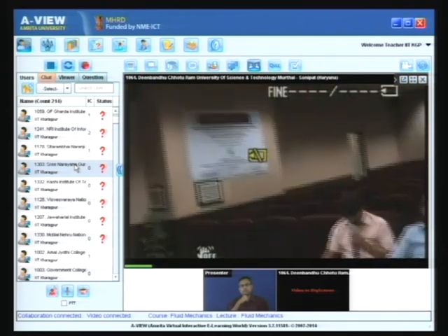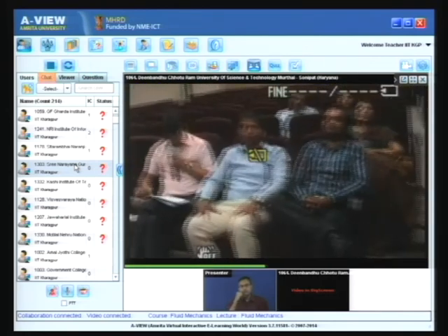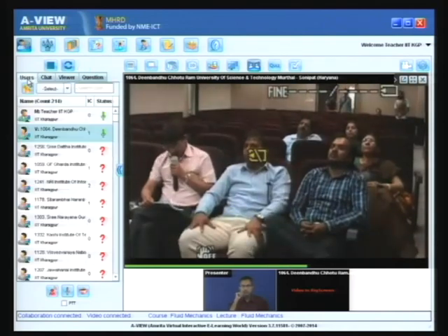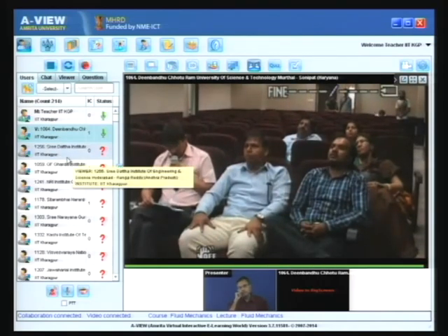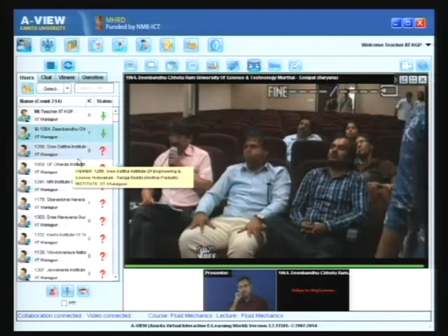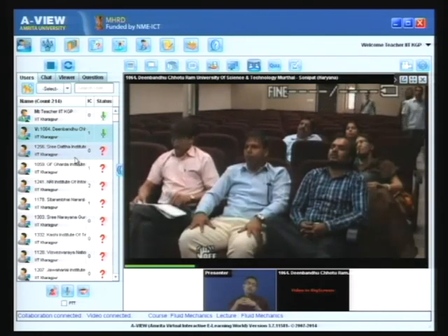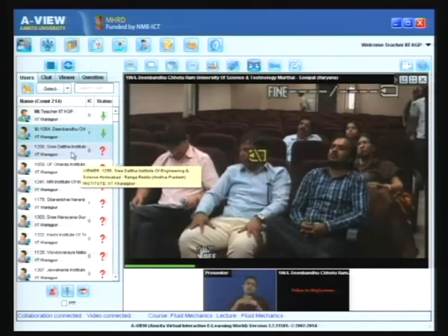My second question is, in the absence of body couples, tau ij is taken as tau ji. What is this body couple concept? Please elaborate. See, body couples means that just like body forces, there can be couples.